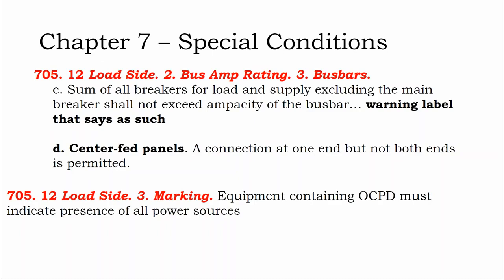So equipment containing overcurrent protection devices must indicate the presence of all power sources. So an electric service panel has to say, hey, this is a solar circuit right here, regardless.